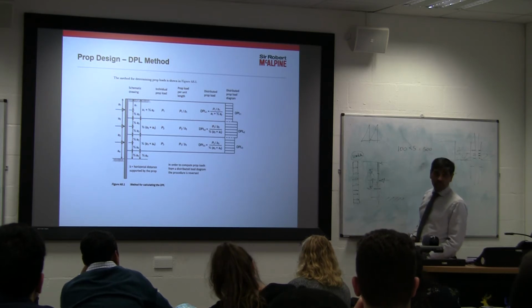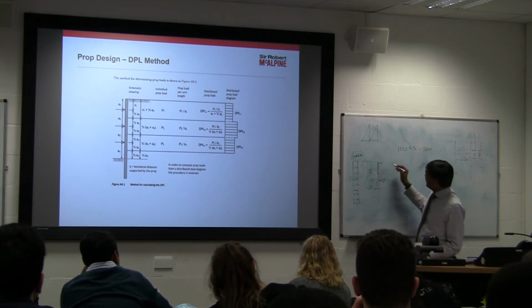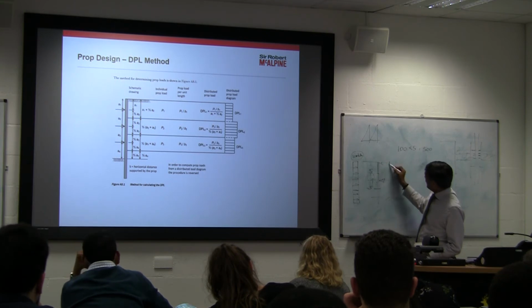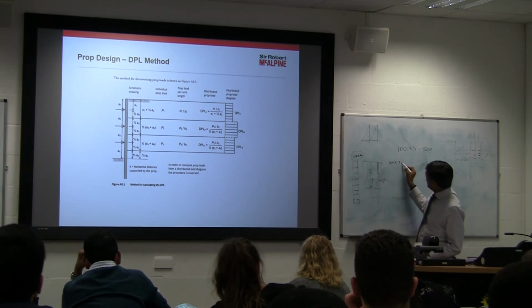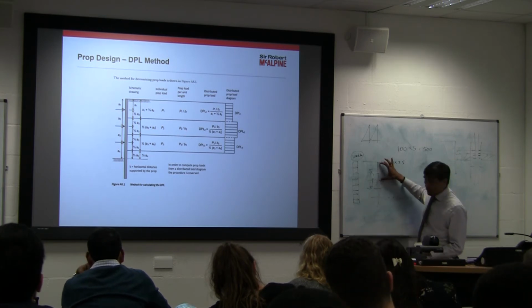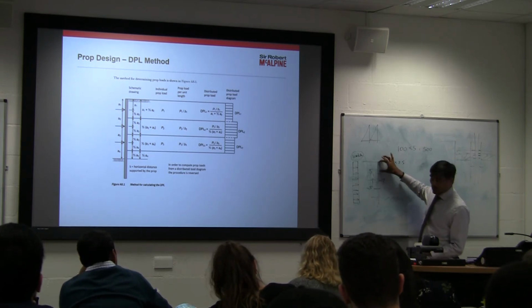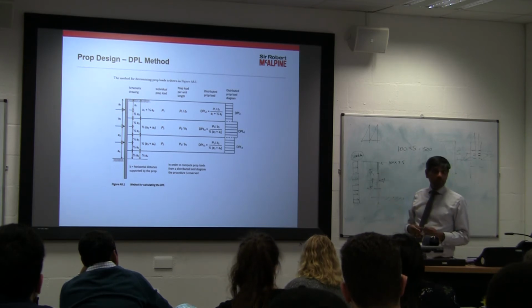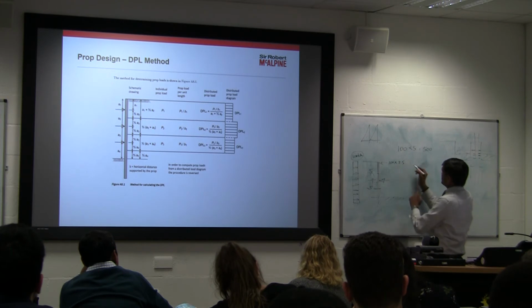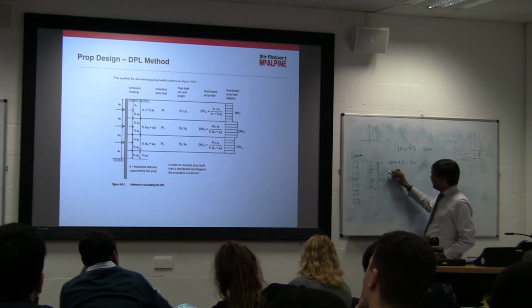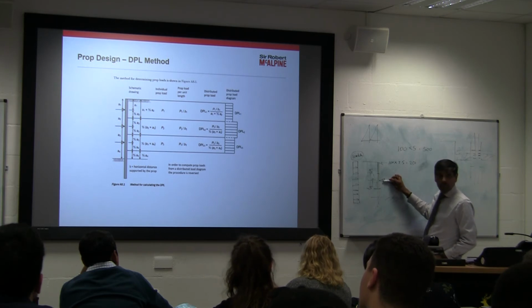Yeah? Makes sense? Whereas this one will have a catchment area that is half of this spacing. So this will be 100 times 2.5 is the load. Because the spacing of the props is 5 meters, half the load will go in there, half the load will go in there. It's like a simple beam, yeah? Simple concept. So once you know this is 250, you can see the top ones will have less load, bottom ones will attract more load.